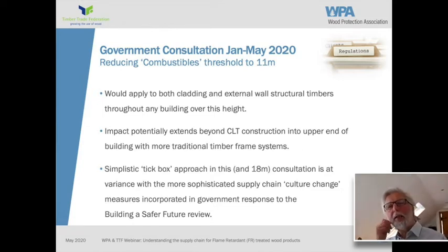So yes, step 2 of this consultation and review of building regulations. Essentially, the consultation that's ongoing at the moment, and they've extended the closing date for responses to the 25th of May, you've got 4 days left if you haven't done it yet, is to further tighten these controls and reduce the threshold to 11 meters. And as I say, this would apply to both cladding and external wall structures.